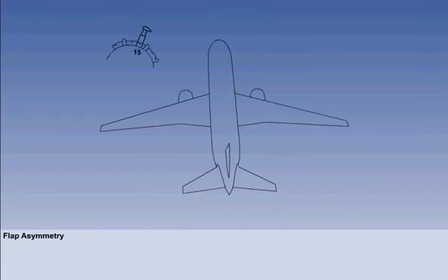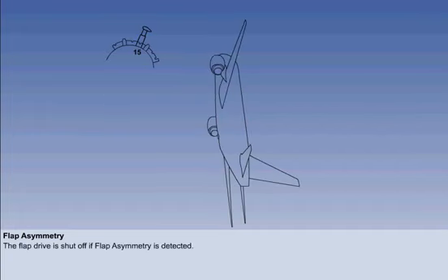If a flap selection is made, and, due to a fault of some kind, only the flaps on one side move, the rolling moment generated can be greater than the pilot can oppose with roll control. Flap asymmetry must be prevented.